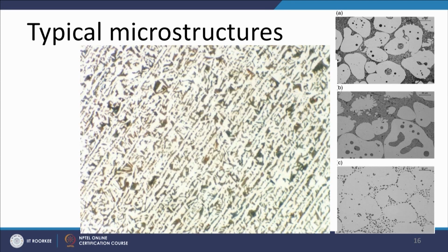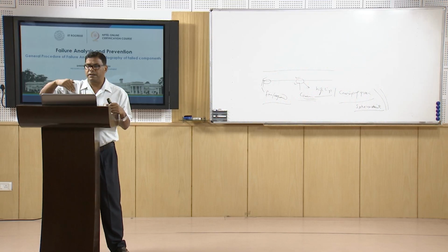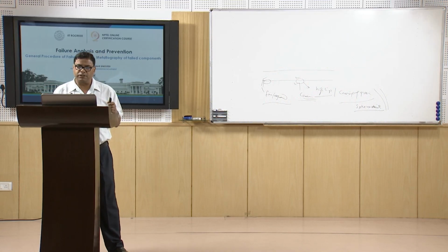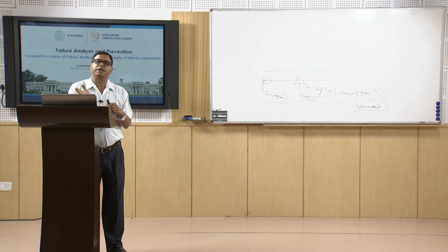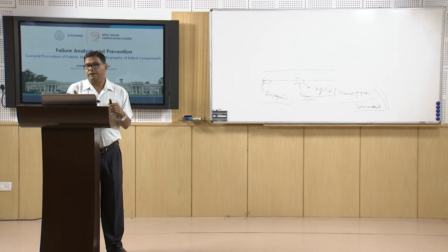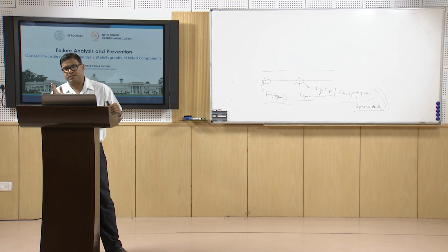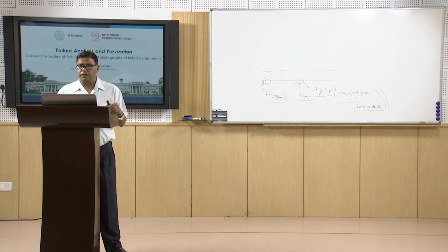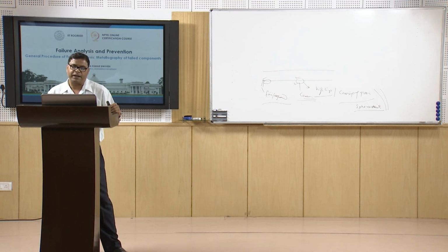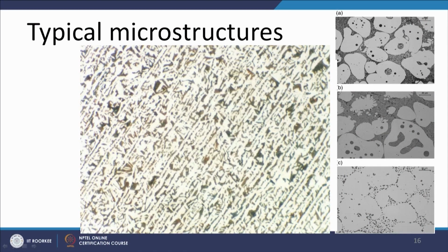This is another structure which shows that one grain is in one layer, then another grain is in another layer. Such grains where bands of particular phases are present are termed a banded structure. Here the ferrite layers are present continuously. So, this is not considered a good structure where one type of phase is present all along the length.